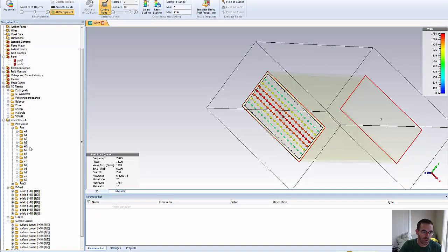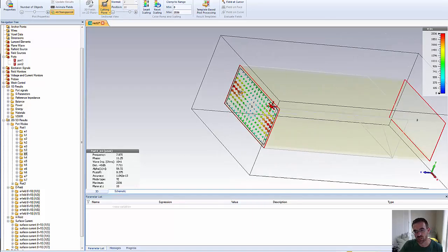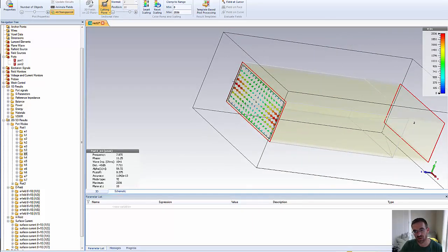We can go up to the higher order modes. So take a look at the next mode, and this is a mode where now I see that I've got electric field pointing in this direction, this direction. Let's animate it and see what happens. Okay, so I've got some interesting field distributions here. Let's take a look at the magnetic field that goes with it. So that's one of the 1-1 modes that I'm seeing there, where the electric field goes from maximum positive through 0 to maximum negative.